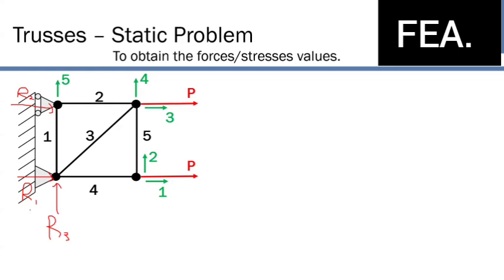So in this case, we can pretty obviously see that there's not going to be an R3, right? That R3 is not going to be resisting anything external. There's not really a moment that it's going to need to resist, and it's kind of clear that R1 and R2 are just going to be equal to P. So we don't even need to worry about R3. We'll just remove it and make our solution easier or a little more clear, okay?